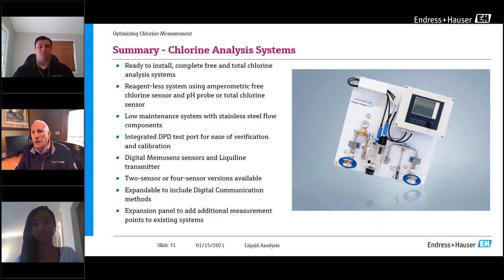You can imagine that the pH doesn't go any lower than that, because we certainly don't want drinking water that's real acidic. So that's why the pH is done to that level, to get it right around neutral, or a little bit less than neutral. If I showed you the curve of pH versus hypochlorous acid concentration, you would see that it's right around that 6.3, 6.5 value where the curve flattens out at pretty much 100% hypochlorous acid. So it's ideally where you want to operate.